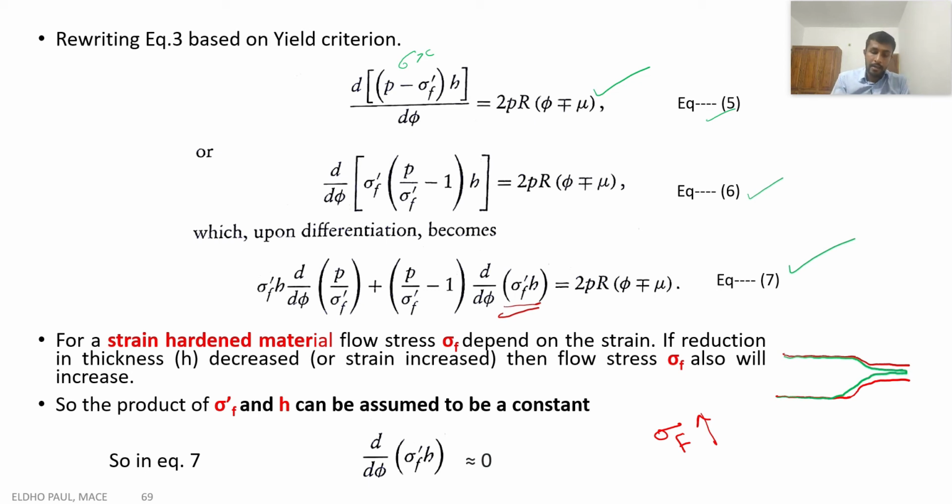In the first case, I reduced to S1. The second case I reduced to S2. So when we compare the strength of the two components, the final product with thickness S1 has less strength than the S2 thickness workpiece or component. This is because of the strain hardening.